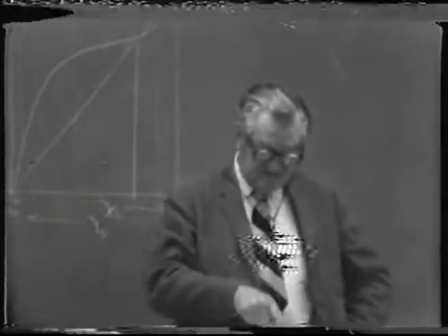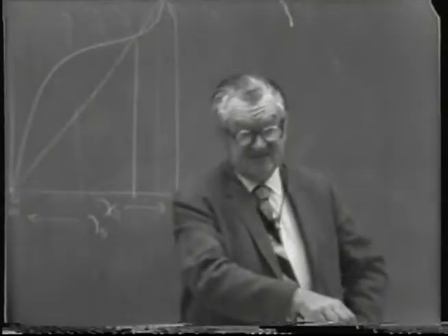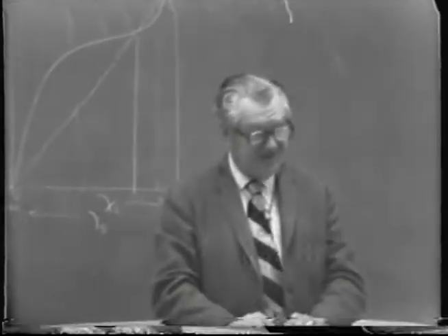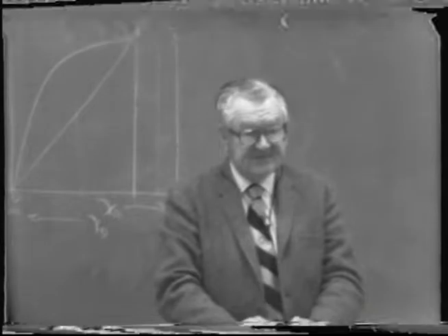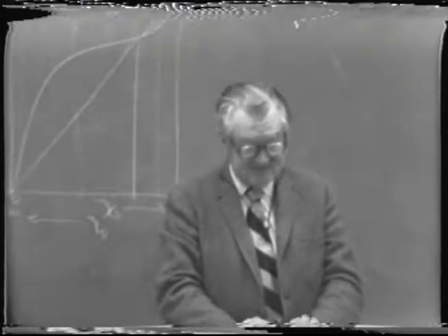In other words, these are values that would give you good operating characteristics. And if you use lower plate spacings for a particular chosen vapor velocity, well, then you would have excessive entrainment, perhaps foaming, and so forth, that would cut down the plate efficiency. So that's the standpoint here.